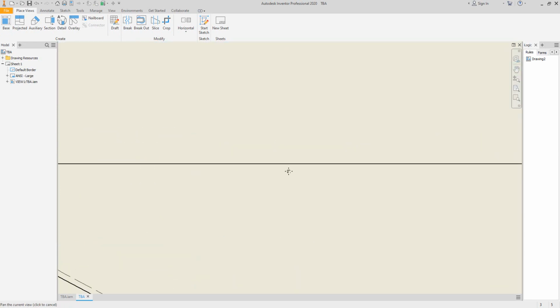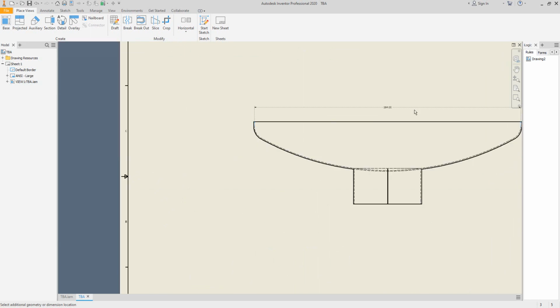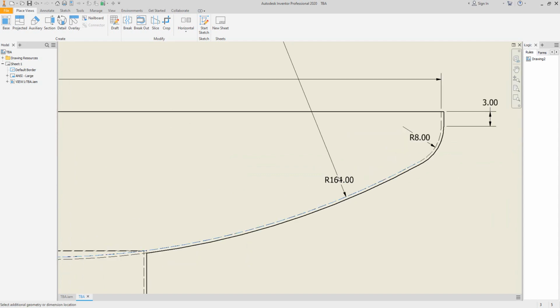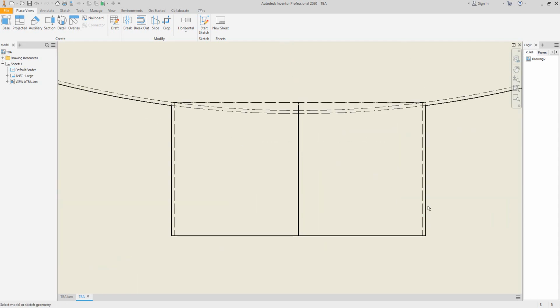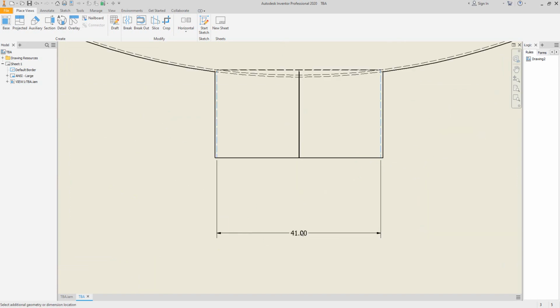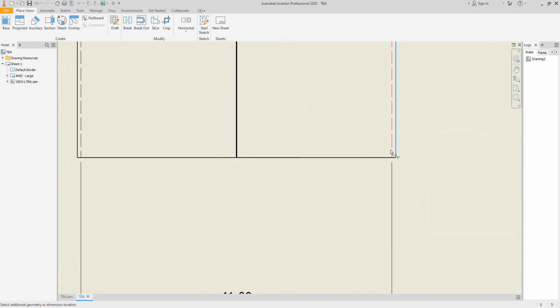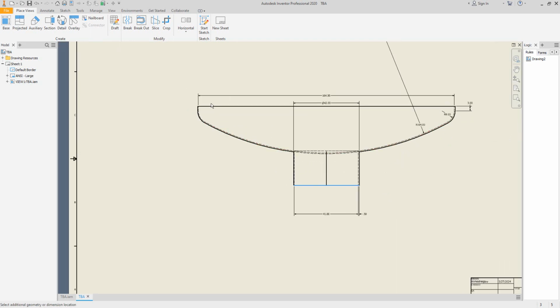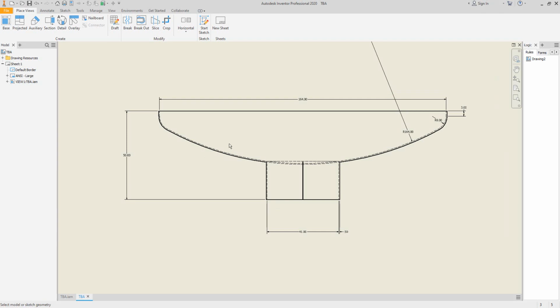So from here, that's the inside diameter, it's 160, and here's the straight flange, the knuckle radius, and here's the crown radius value, and the inside diameter of this nozzle, and here we have the thickness, and the projection from here to there is 50 millimeters.